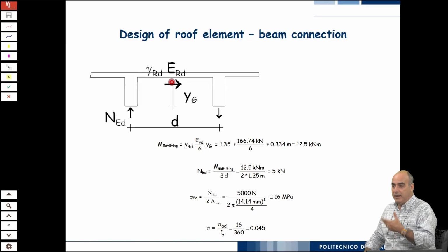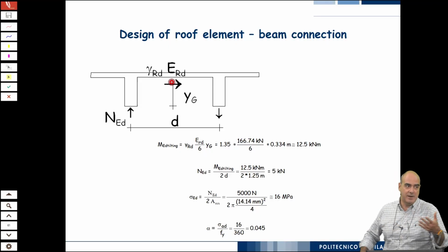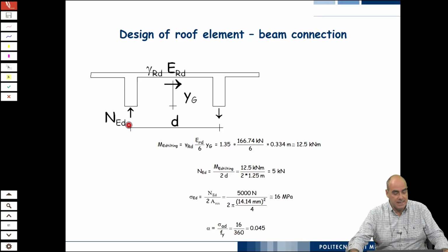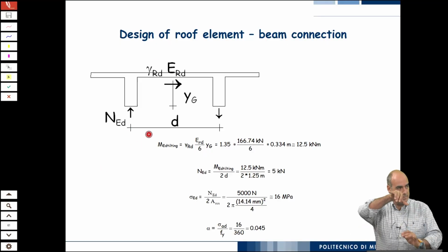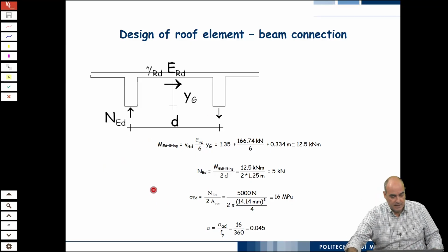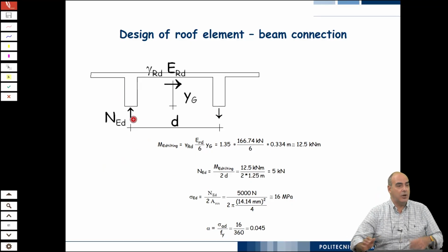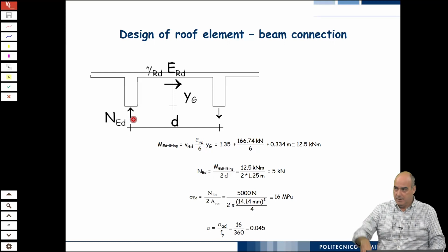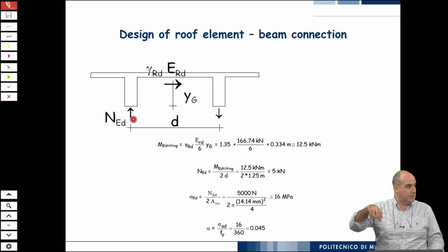So it's applied where the masses are, and the masses here are applied on the top. So this also has an uplifting effect on the column, which means that, since this action is cyclic and can come one way or the other, you also have to check the connections for pull out from the beam.